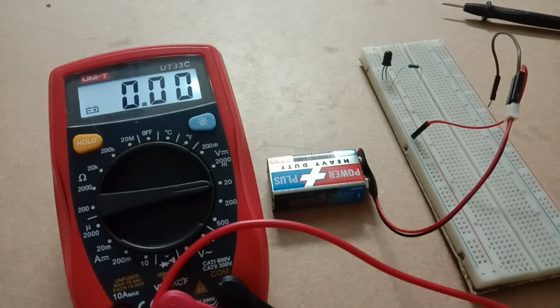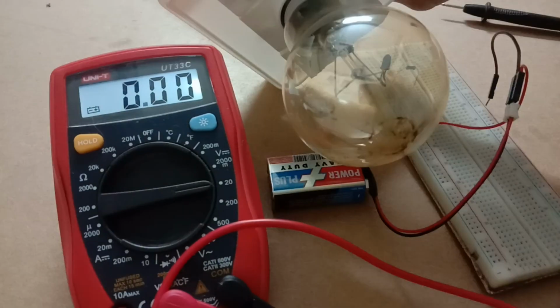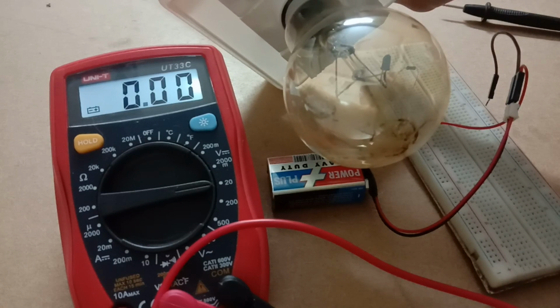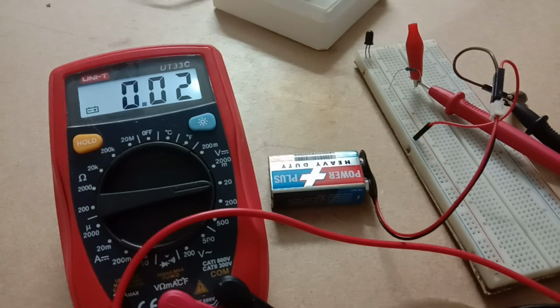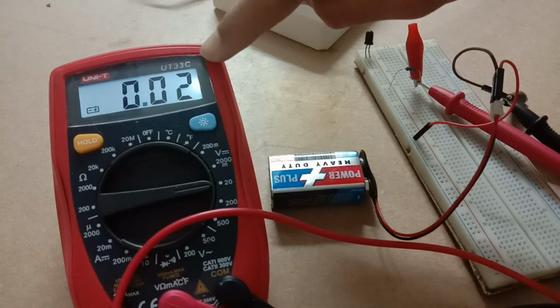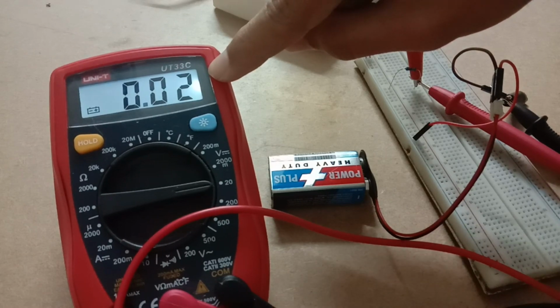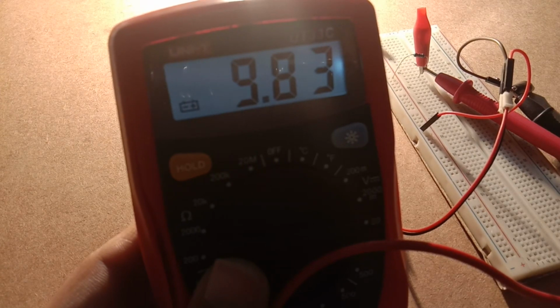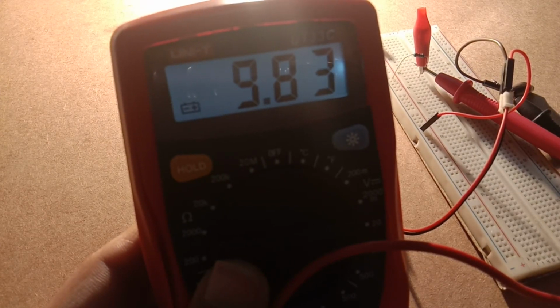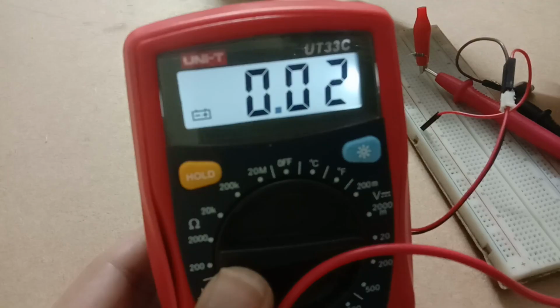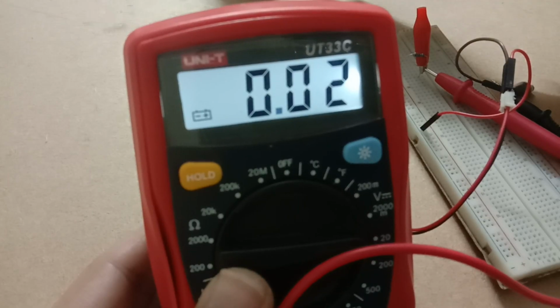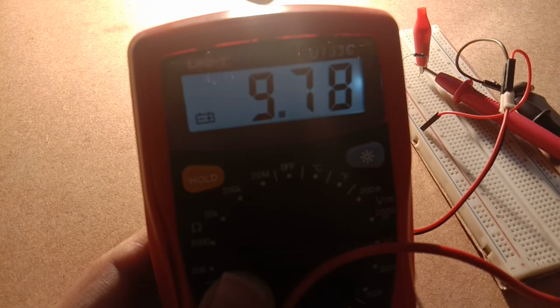So here's my setup, which I have made to show you guys how an IR receiver works. I will use a 100-watt bulb as a source of IR radiations, which I made in one of my previous series circuit videos. So I have connected all of the components for the circuit to check the IR receiver, and you can read the voltage across the IR receiver, which is currently 20 millivolts, and see how far it goes if I turn on the IR source. You see the voltage rises up to 9.8 volts, and if I turn off the bulb, the voltage again goes to 0. Now if I again turn on the IR source, the voltage again climbs up to 9.8 volts.